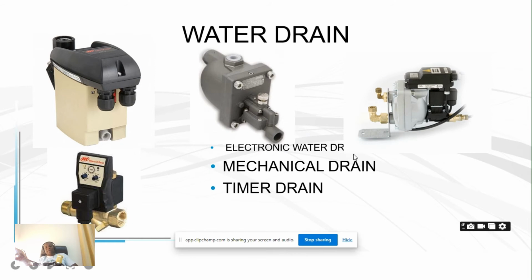Now we have the mechanical drain, which is this. It doesn't need electricity, it doesn't need any cable connection, it just needs air in the header, and it will purge. Once it rises, there is a level gauge, and when it gets to the level, it will purge on its own. It's not always as effective as this, but it's used mostly where you cannot get an electric connection. But this is an electronic water drain, EWD, and this one needs power.